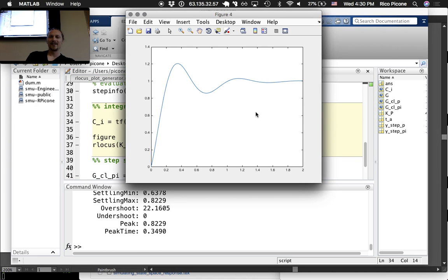Oof. So pretty good. I think we lost some settling time there, but we gained some steady state error. So this is one of those things. It's a bit of a trade-off between your different performance requirements. In this case, the setup would be 1.2. Yeah, and so my percent overshoot here is like 21% or something.